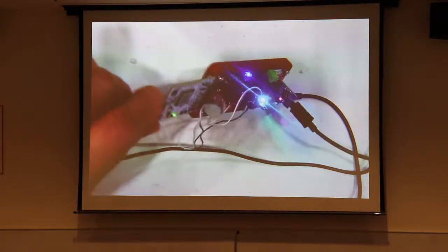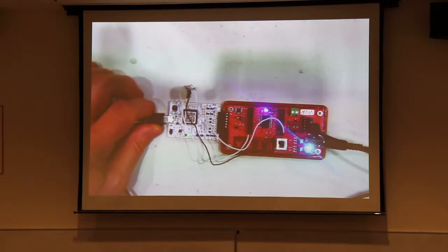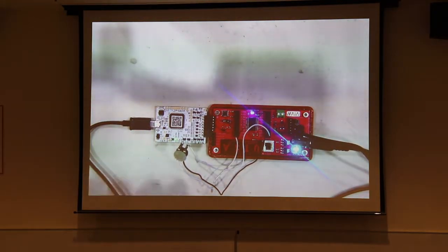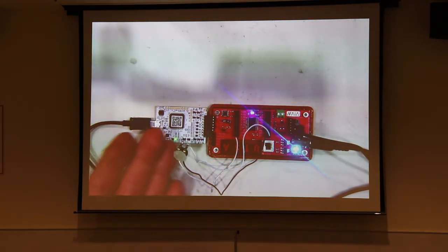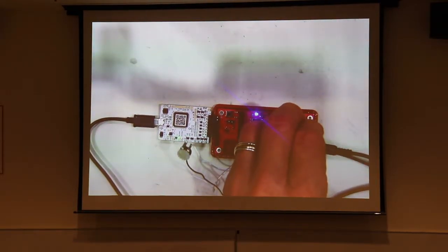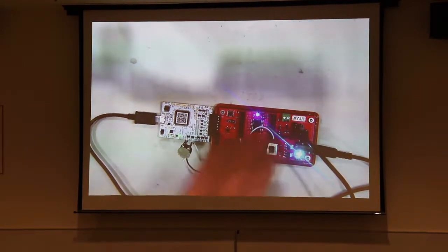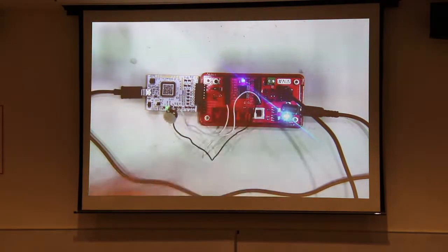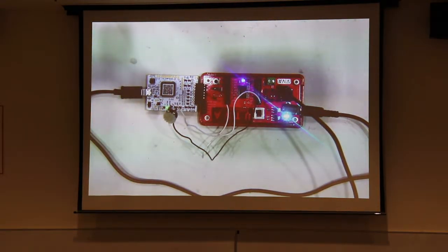And then I also plug the potentiometer in here, and the way this is working, it's going to read the potentiometer, write out the value of the potentiometer through the UART cable, and then also write the value of the potentiometer into the duty cycle register for the PWM. The PWM is set up to drive the blue color on the LED, and the other colors have been turned off with this particular code. I'm not going to go through the code in too much detail because you've got it in lab. And it's actually a little bit of a pain in the butt.